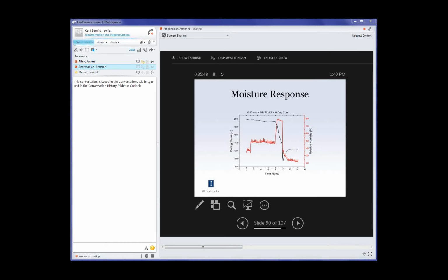Plenty of other research has shown that there is a lot of irreversible strain that can build up in concrete, and we're showing some irreversible curling strain that can build up in concrete. It was kind of cool because no one had ever really looked at irreversible curling strain. Most of the people were looking at temperature effects and how the temperature the concrete is placed at, it has sort of built-in curling. But here, we're just changing the humidity and we see this drastic change. This mix had no lightweight in it, had about 100 microstrain drop in strain when we up the humidity.